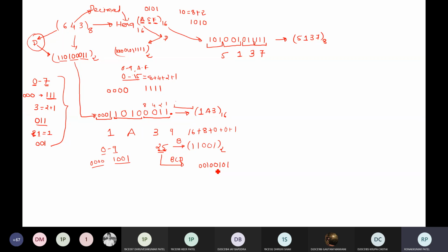So it will take any digit and represent the digit into 4 bits. So how many bits are required here? Total 8, and in this case 1 2 3 4 5, so 5. Here 8 bits are needed, so 3 more bits are required. So in BCD, when you convert a number into BCD, it will take more bits, right? That's why we usually prefer this binary representation.